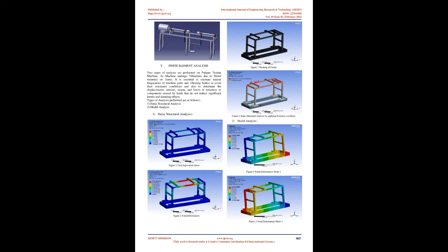The principal function of the second shaft is to rotate the specimen while it is under the action of bending moments from the dead weights applied at the left arm of the clamping system. The shaft is threaded to allow for screwing of the specimen chucks.